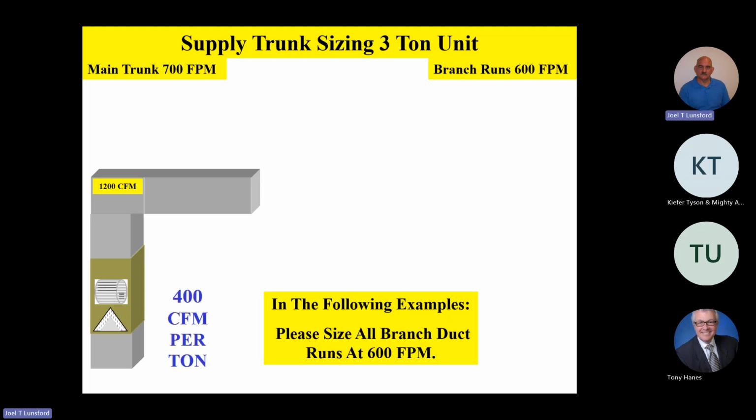The point is we have to know the CFM in each space before we build a duct system to it, right? So we're going to presume right now that you know how much CFM you want in each space. And we're also going to presume that I know how much CFM on the PowerPoint I want in each space. But just keep that in mind. Before you build a duct system, be sure you know how much CFM you want in each room or in each space. So with all that said, our first takeoff here is going to be 135 CFM into that conditioned space. I've already determined that by whatever method I use.